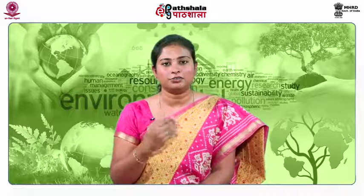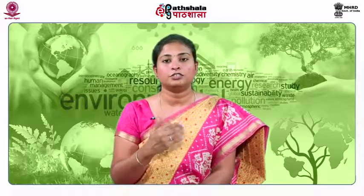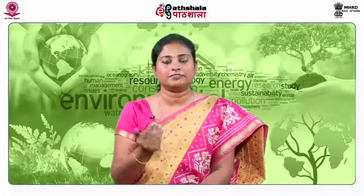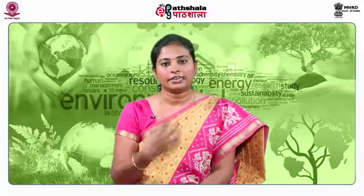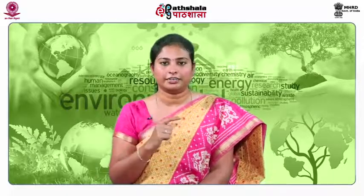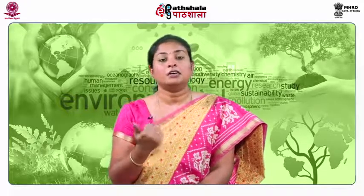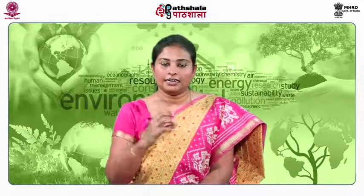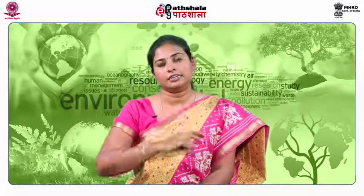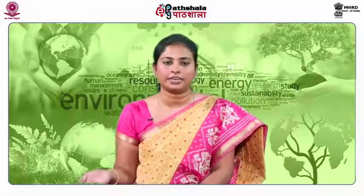Then comes the cellulose and lignin level. You have to measure the cellulose and lignin level in the bioreactor, which will help in determining the phase of biological activity. Then the leachate yield and quality will again tell you the rate of degradation occurring inside the landfill bioreactor. Short circuits in the leachate system can also be determined. Then by characterizing the leachate, you can analyze what phase is occurring inside the landfill bioreactor. Like the acetogenic leachate will have a different characteristic and the methanogenic leachate will have a different characteristic.